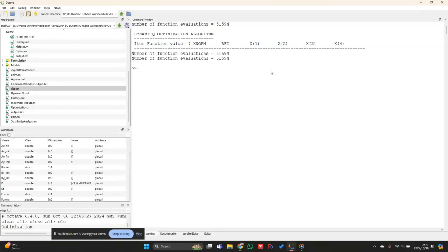Since you're working now with the forward difference method, what essentially happens is that for each gradient calculation, or for each design variable that you specify, an objective function at the step size needs to be determined as well. So if you have 4 design variables, then 5 function calculations are going to be performed for that iteration. So one function evaluation is going to be at that value of the design